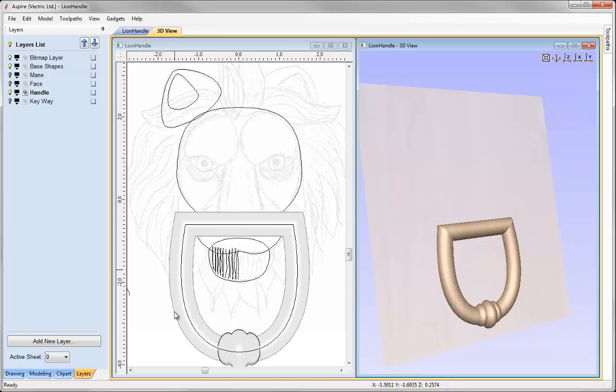Now, in order for us to use this as a working knocker, it would be okay as is. However, we could get a little bit of slide from side to side when using the handle as a knocker. So what we could do is look at modelling in a shape that's going to lock the handle within the recess of the base shape and within the recess of the bottom of the face shape, and that's going to house that nicely in place so that we don't get any movement from the handle side to side. We only have one way that it can move, and that's up and down in a door handle knocking motion.